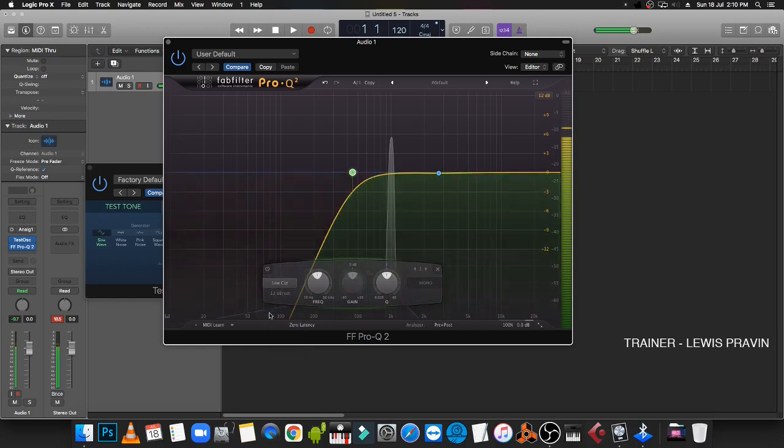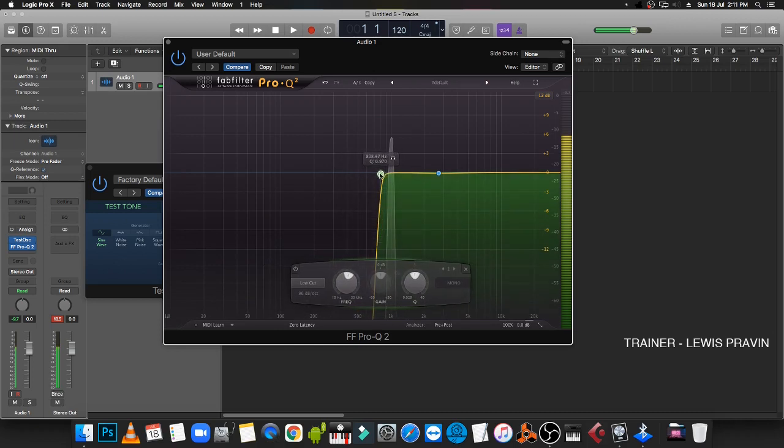So I select a low cut, and this is the slope. As I increase the decibels per octave, you could see the slope becomes very abrupt, so we are cutting it right there. If I keep decreasing the decibels per octave, you have a gradual cut. You could see a gradual cut forming on the filter. So let me now choose a very steep slope and move it closer to this particular graph displayed.